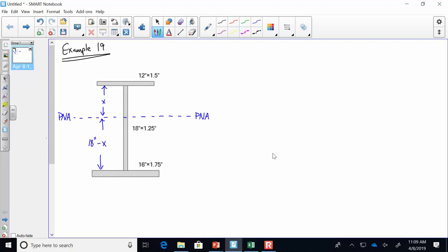Now, what we'll do is assume positive bending, so everything above the neutral axis is in compression. Everything below the neutral axis is in tension. So let's see if we can define the area in compression. The area in compression is this area right here, all this red shaded area. So what's a good formula for this? Somebody help me out. What's the area of the flange?